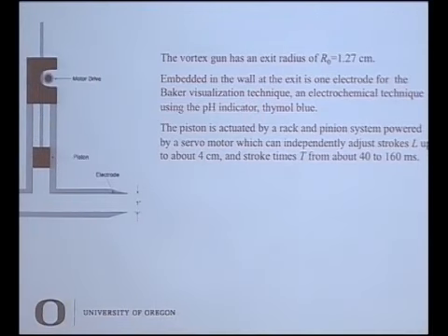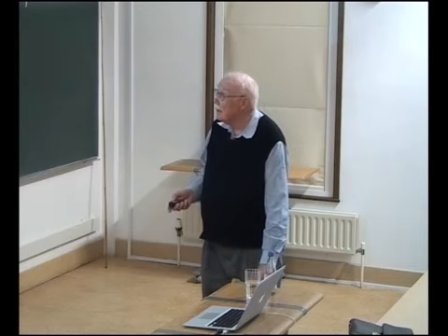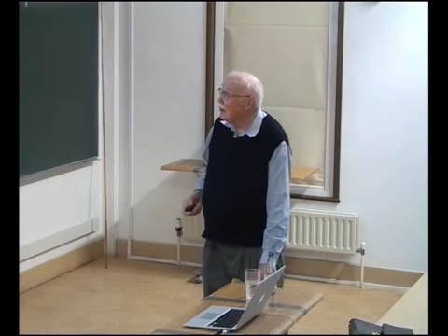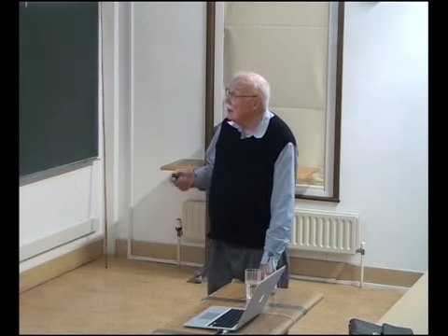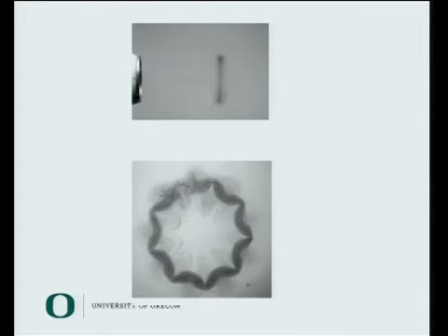But anyhow, what matters is the stroke length, which I call capital L, and the stroke time, which I call capital T. With this particular gun, you can have strokes up to about 4 centimeters and stroke times from about 40 to 160 milliseconds. So they really go quite fast.